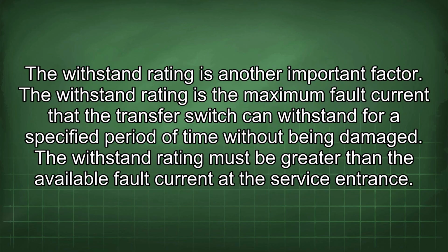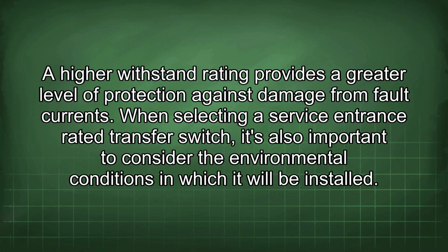The withstand rating is another important factor. The withstand rating is the maximum fault current that the transfer switch can withstand for a specified period of time without being damaged. The withstand rating must be greater than the available fault current at the service entrance. A higher withstand rating provides a greater level of protection against damage from fault current.